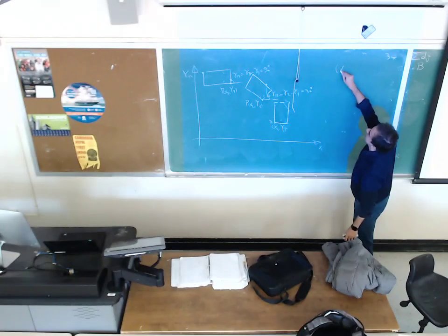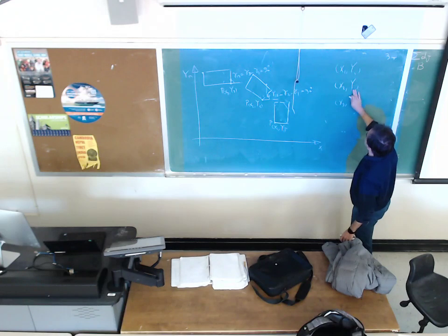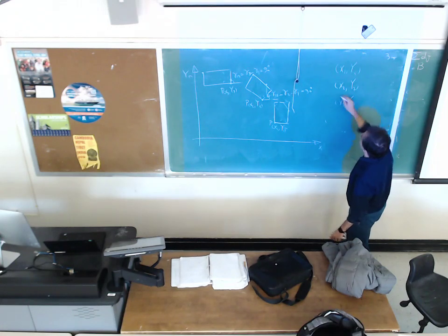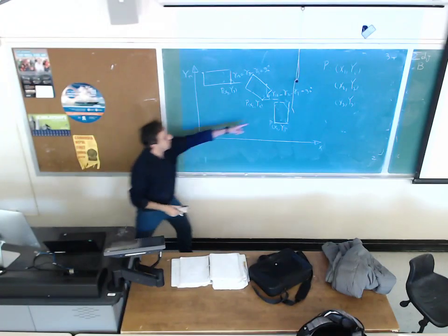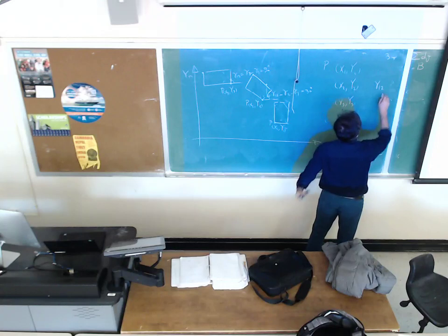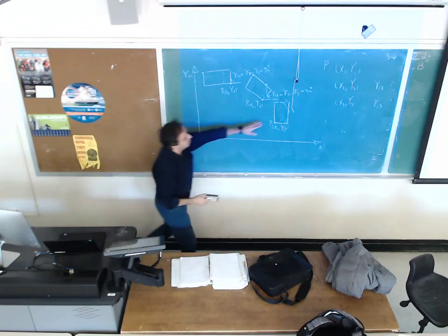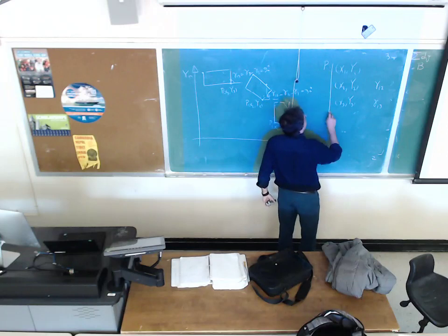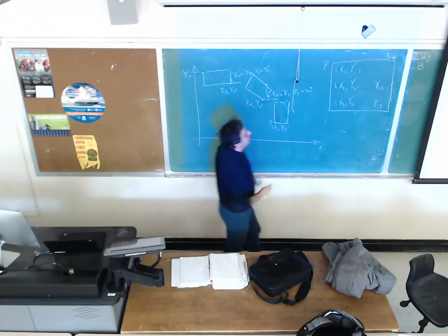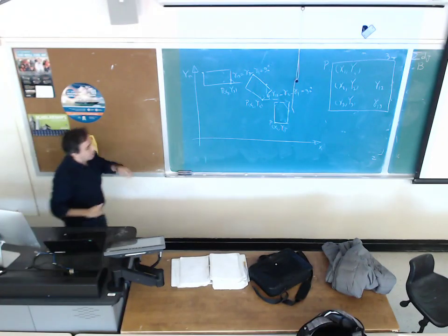Just presenting position of 1 point in 3 desired positions plus gamma 1,2 and gamma 1,3. What would be the rotation of rigid body from the first precision point to the second precision point and from first to the third? If I provide this information, this is going to represent the desired motion that we are looking for.